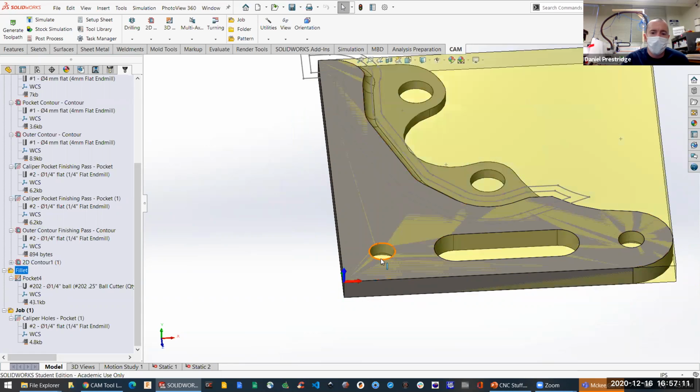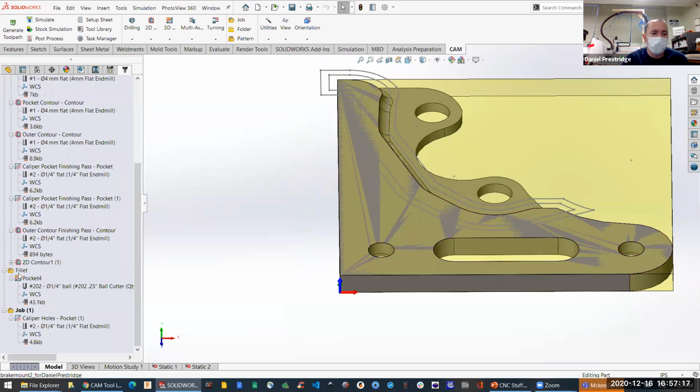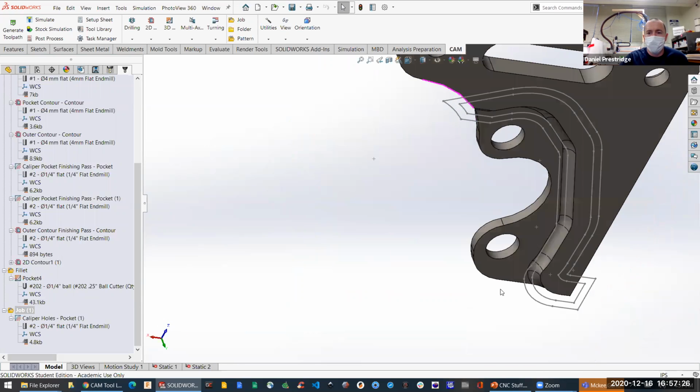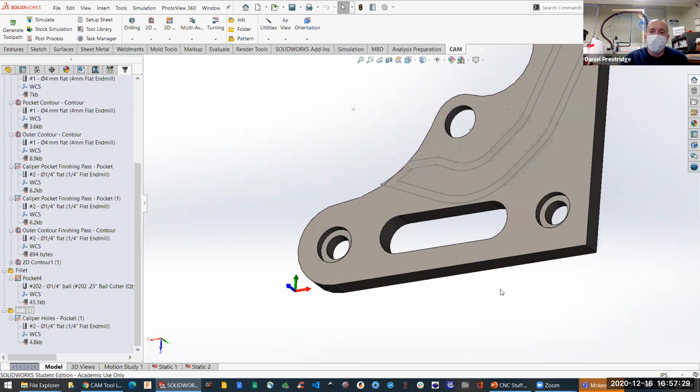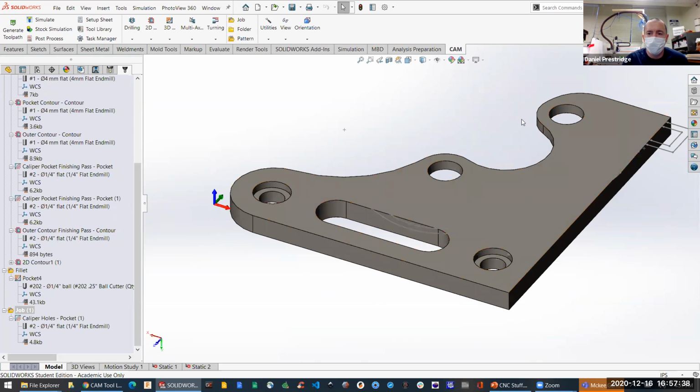But then we flipped it over, and now, so I'll show you this guy. And then when we flipped it over, now you had to make sure that it aligned with the machine again. And that's what we did. We put the X this way, the Y this way, and the Z this way. And we're going to be cutting these guys based off of that one part that we kind of identified as our origin. So it goes definitely deeper into that, but that kind of gives you an idea of at least the setup.